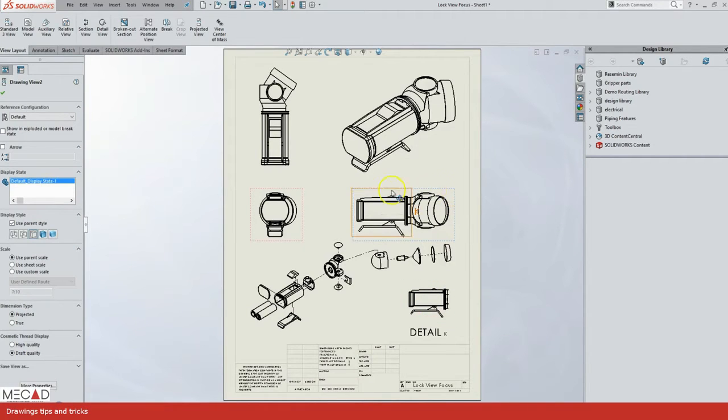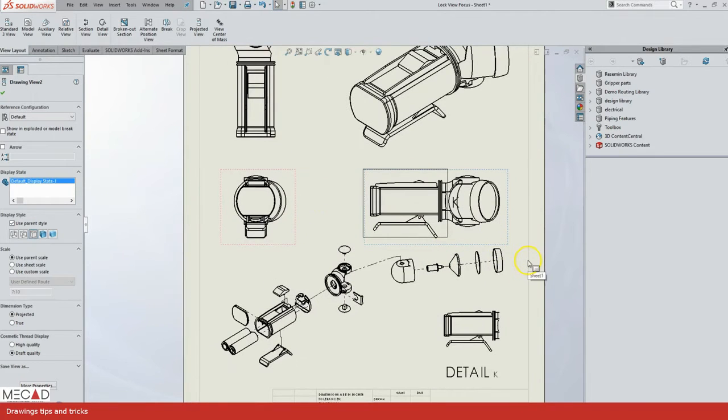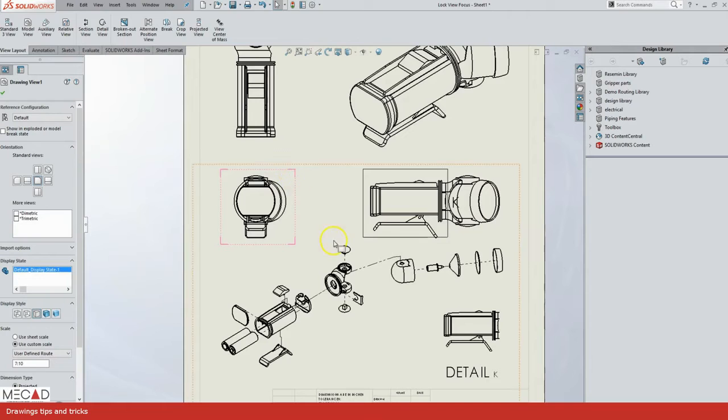And that view is locked, that sketch is locked to the view. To unlock it, it's automatic. As soon as you create a view like that, the view will be unlocked and you can carry on. How do you see if it's unlocked or locked? Notice that there's clean dotted edges on the side of the view focus. If you double click inside of a view, it actually puts a darker frame around it, locking the view. Instead of doing the right click, you can double click. A very nice little trick to use as well.